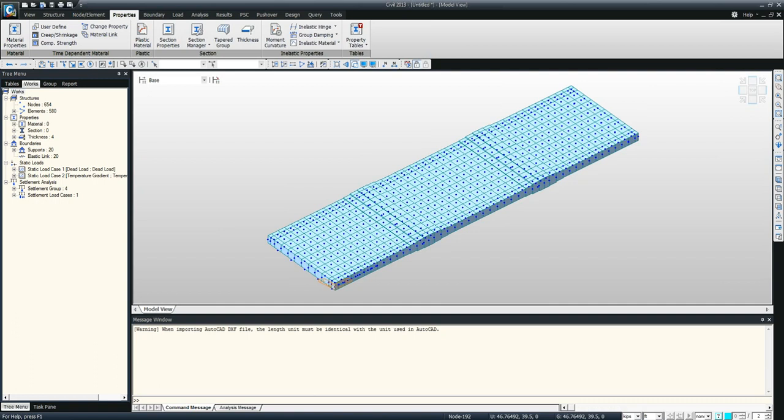When you model the construction stages, then you can model the girder as non-composite in stage 1 and composite in stage 2. So this way, whatever load that you apply in stage 1 will be defined on the non-composite cross section, and from stage 2 onwards it becomes composite, so the live loads will be acting on the composite cross section. And definitely we are going to talk about it when we do the construction stage analysis scheme.